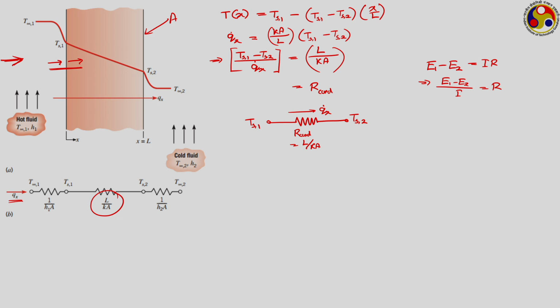This is just the convective boundary condition, nothing else. So, let us apply the convective boundary condition on the hot fluid side. Then the amount of conduction happening is minus K A dT/dx at x equal to 0. That is the conduction happening on the interior side, and on the exterior side of the face what is happening?